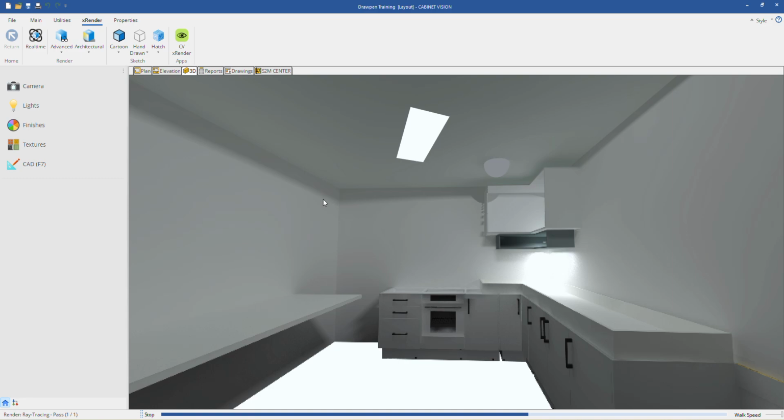Go to the drop down under architectural, full architectural. Wow. Sure, that looks good, right? Not really. That looks kind of horrible. You see how our lights are physically visible like this. You remember that setting that said show in X render?